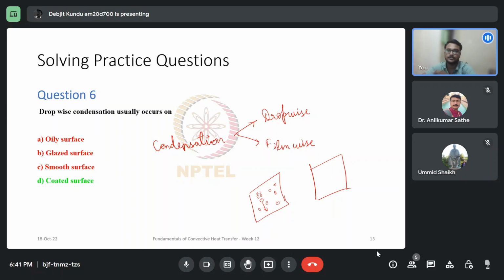there are no individual droplets, but instead a layer of liquid gets condensed from the vapor phase, and it forms a boundary layer sort of a thing. Not a boundary layer per se, but the kind is similar, and we saw the math of it as well. So they do resemble each other. There is this film thickness delta, which is analogous to the boundary layer thickness delta as well. But of course, those are very separate things. Let me give this warning sort of. They are similar but not the same.